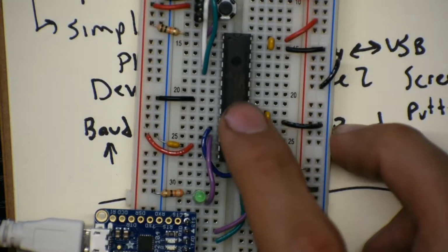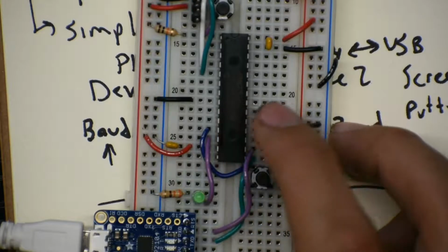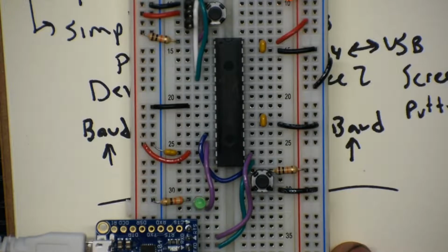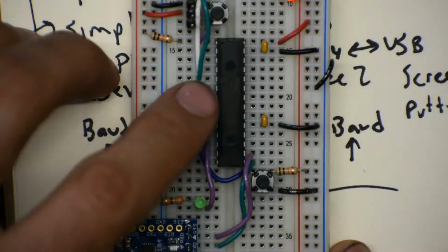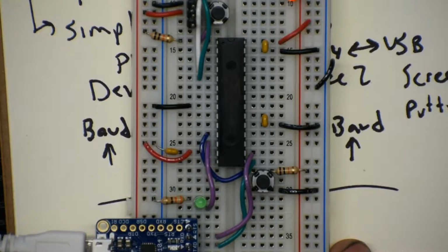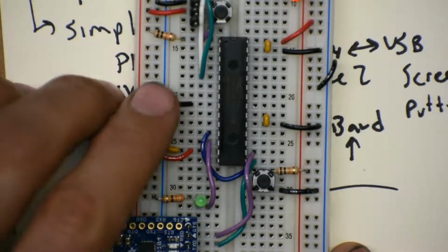This internal resonator isn't as good in terms of like when the chip heats up, the frequency might shift a little, but it won't be so bad that we'll even notice that. If we were trying to do USB communication directly with a PIC, they don't recommend using the internal oscillator. That's why I typically use the external oscillator. We're gonna ditch that right now, and I'm gonna show you how to adapt the code that you wrote for the earlier homework, so that everything still works.